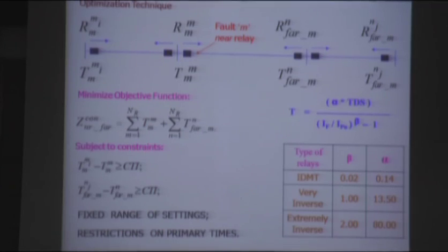Now you may ask how it can be made possible that the same relay will act faster and also act slightly delayed by the same setting. It is because the nearer the fault to a location, the fault current will be more at that location, and fault current will reduce substantially as it moves away from the location of the fault. So when it acts as backup relay, the value of the fault current sensed by that relay will be smaller.